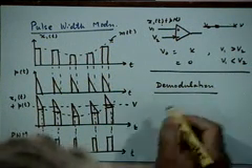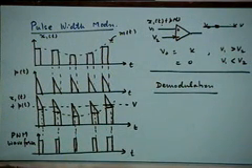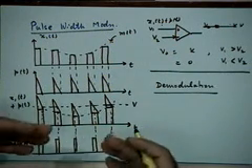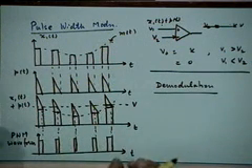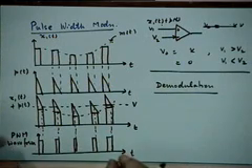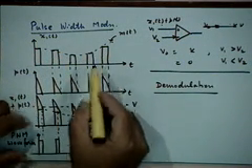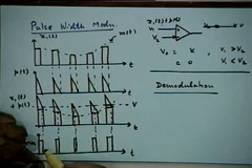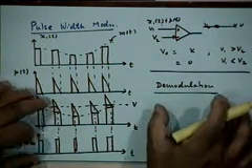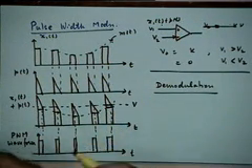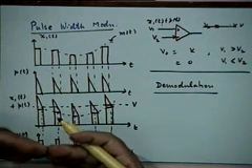To look at how you get the original message waveform back. As you can see, this is a different kind of sampling. You are still doing sampling, but the sample information, the amplitude of the waveform, is not directly embedded in the amplitude of the pulse. It is embedded in the width of the pulse. Now, to look at the demodulation, what was the demodulation based on for the case of PWM?